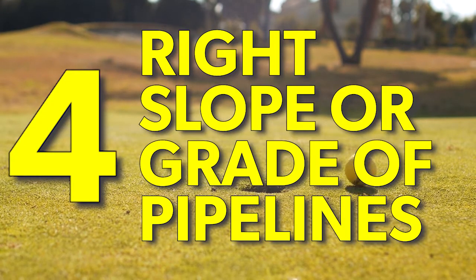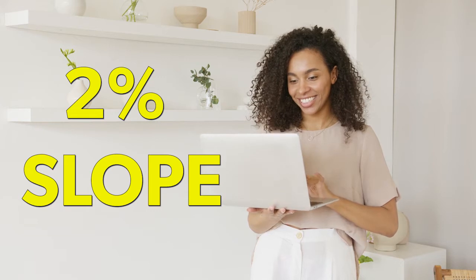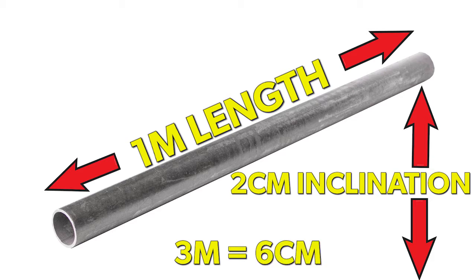4. Right slope or grade of the pipelines. The ideal position of horizontal waste pipe were those installed at 2% slope, meaning the pipe was installed with an inclined ratio of 2 cm per meter length. For instance, a 3-meter pipe installed as a wasteline will have an inclination of 6 cm.